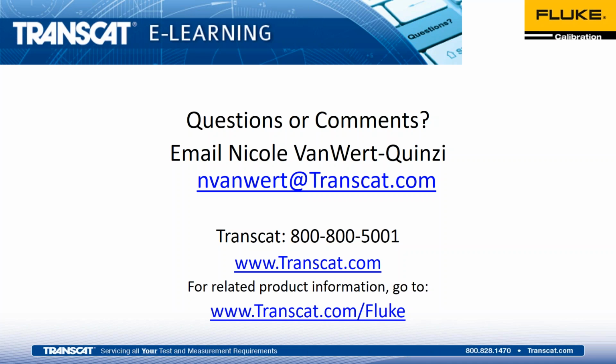Hi, if a unit under test is odd-shaped or does not fit completely, can we place insulation on the end of the block or well? I've seen people do this, so yeah, you can do that. The bigger question with the odd shape is the immersion. How far are you getting it down in there is the bigger concern. Because even though you're insulating from the top down, if you've only got, say, a few inches into the actual heat source, that's going to be the bigger concern for the heat getting conducted properly to that sensor.